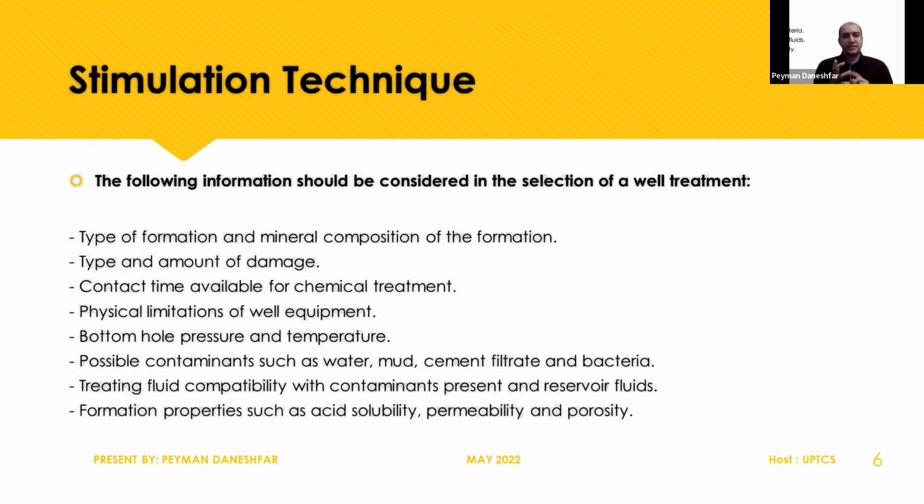Some parameters are the formation mineral composition, the amount of the damage, the chemical treatment, or the limitations in some of our equipment in jobs, bottom hole pressure and temperature, mud filtrate or cement filtrate, the compatibility of our chemicals with the well, and formation properties such as solubility, permeability, and porosity.